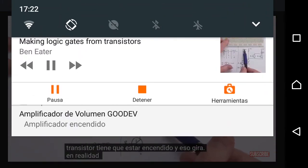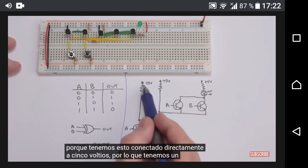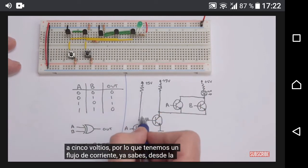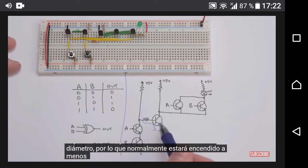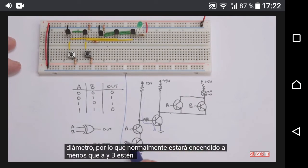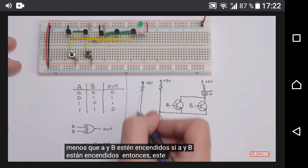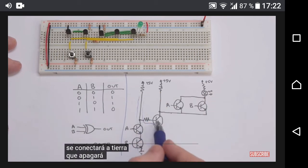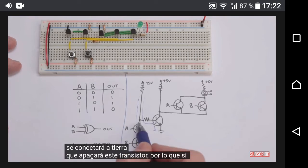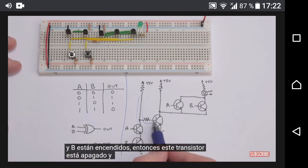And that transistor is actually normally on, right? Because we've got this connected right to 5 volts. So we've got current flowing from the base to the emitter. So this will normally be on, unless A and B are on. If A and B are on, then this node here is going to be connected to ground. That'll turn off this transistor. So if A and B are on, then this transistor is turned off.